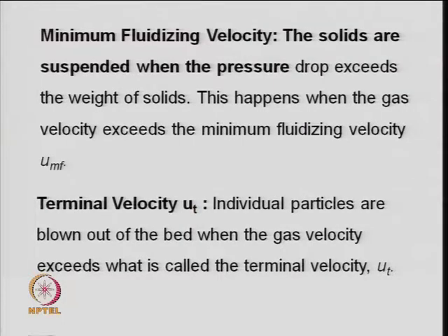And another term is known as terminal velocity. So, terminal velocity is where individual particles are blown out of the bed when the gas velocity exceeds it. So, terminal velocity is basically the velocity at which the particles leave the bed, right. So, it will again depend on the individual size of the particle and their physical properties.